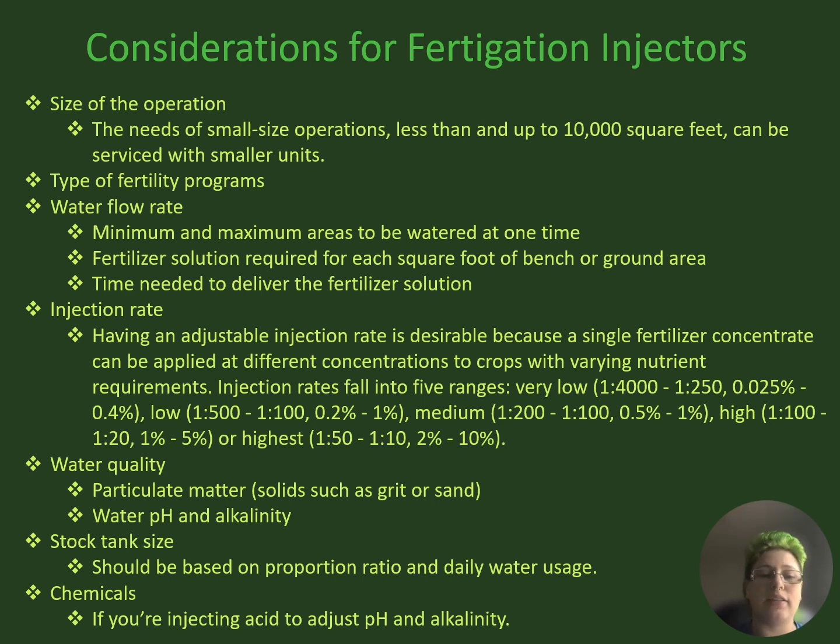If you're injecting acid to adjust pH and alkalinity, you must know about your injector and know that your injector can use acid.